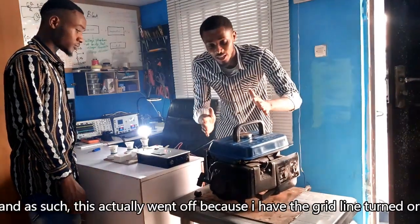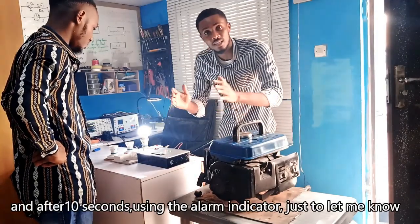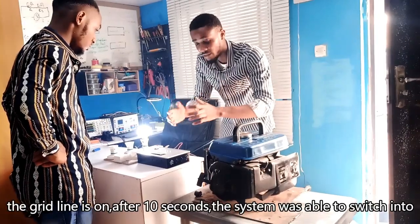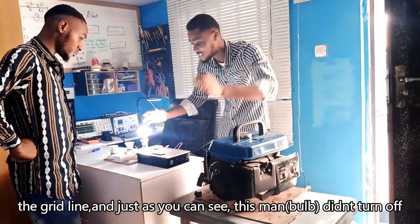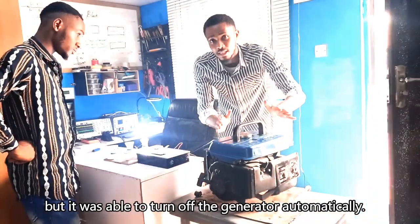And as such, this actually went on because I have the grid line turned on, and after 10 seconds, using the alarm indicator just to let me know that the grid line is on, the system was able to switch into the grid line, and just as you can see, the load didn't turn off, but it was able to turn off the generator automatically.